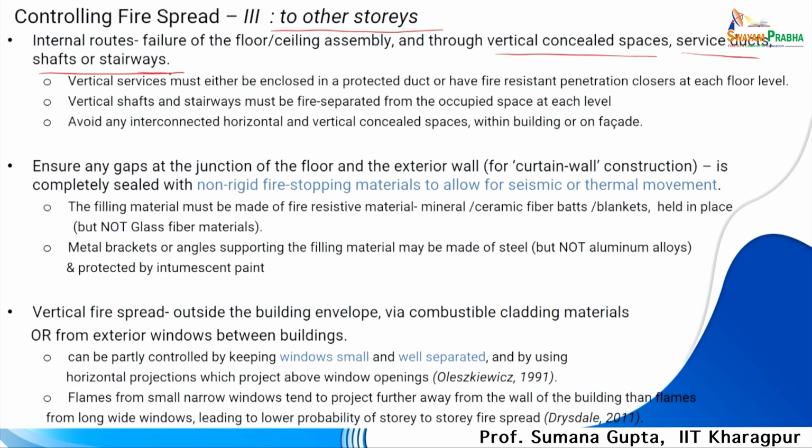What can we do? We can put doors at the points where you enter these vertical shafts, that means the staircase. If your staircase is a fire escape one, you can have a door through which the staircase is accessed, always having an automatic closing control, so that when people run into the staircase the door is always getting closed.